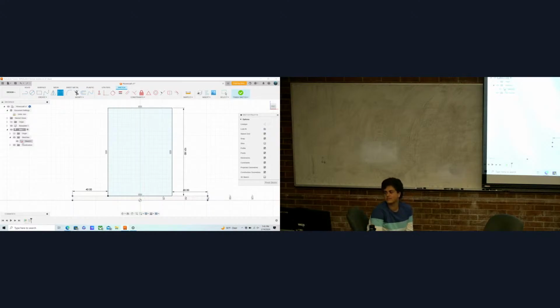And then you want the wall to be 40 millimeters from the outside of the piece. So if you want this wall to be 40 millimeters from the edge, you'll dimension the wall so that fits. Yep, so you select that side, that way. And then you select the point on there, because you want the wall open. So right now you just make sure you actually click the point down. Yep, go. And then that's your placement.